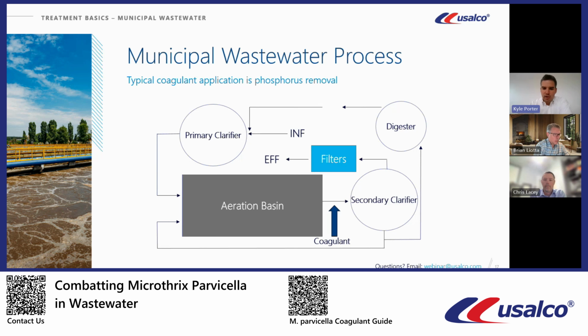So in this case, we always recommend, from a cost standpoint as well, you're going to want to usually put your coagulant as late as you can in your process. And every wastewater plant is very different in terms of how it's laid out, but generally after your aerobic section, your aeration basins, if you have a secondary clarifier, that's optimal. But generally as late as you can be, or somewhere you're going to get a decent amount of shear and mixing in time. But you don't want to put it earlier on because you're going to end up using the coagulant on a whole bunch of things your biology can do the work for you free, and cheaper.